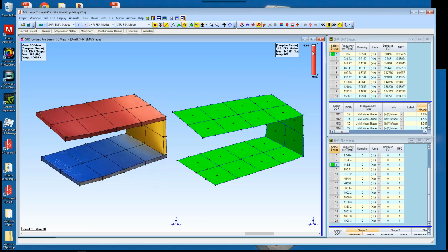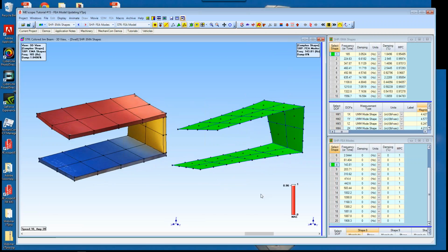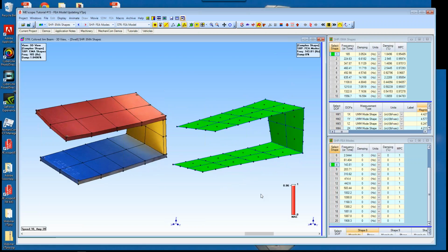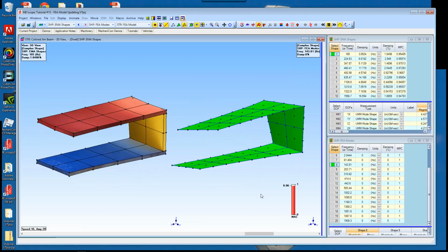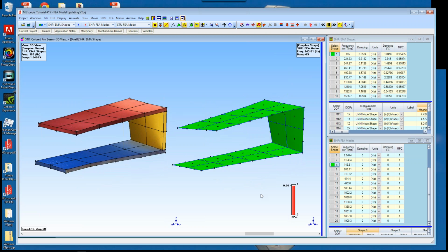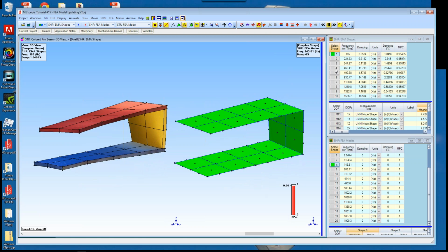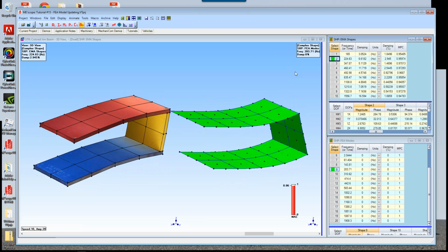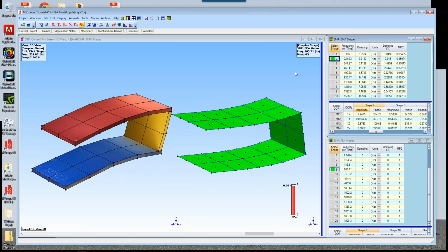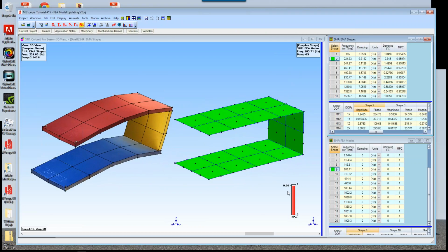So if I put this down here at the bottom, you can perhaps see it a little better. I just dragged it down to the bottom, 96%. So that's basically saying anything above 90% is saying that the two mode shapes are the same. Now let me click on this next experimental mode, and you can see that both mode shapes changed. And again, the MAC value is 96%.